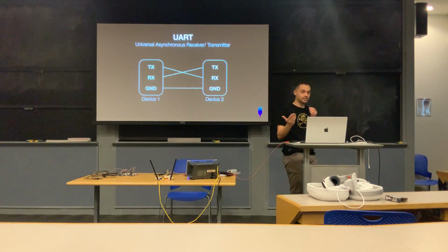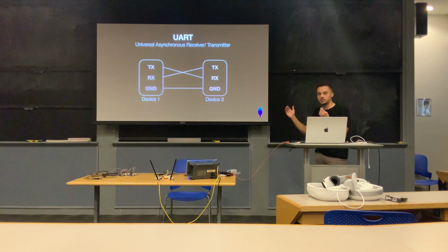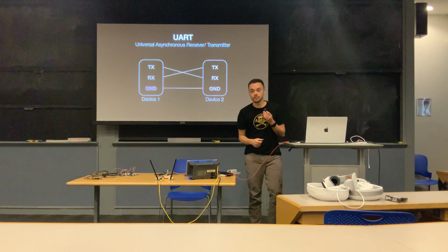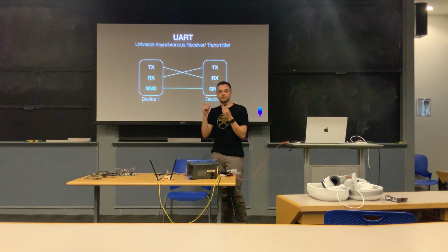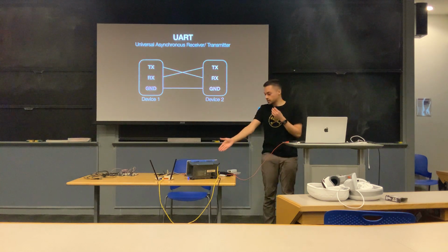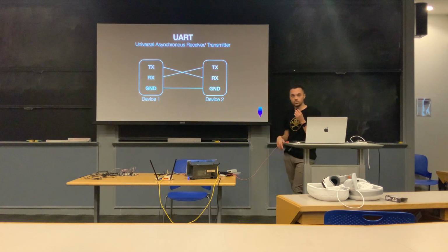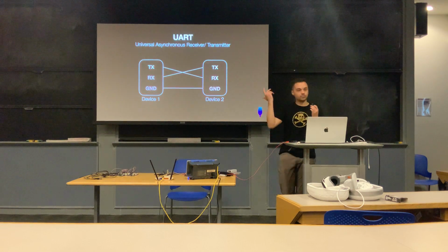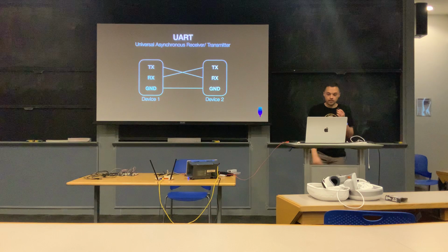So you notice when I connected, I specified the number 115200 as an argument to the screen command. That's actually the baud rate, the actual rate at which we're going to poll these pins. And so to use this UART adapter, you have to specify the frequency. How would you be able to learn this frequency? Well, you could use the oscilloscope. Like we saw, we can actually look and see how these timings are being sent, or you could guess. So the one that I guessed is the most common for routers. So that's a brief look at UART.